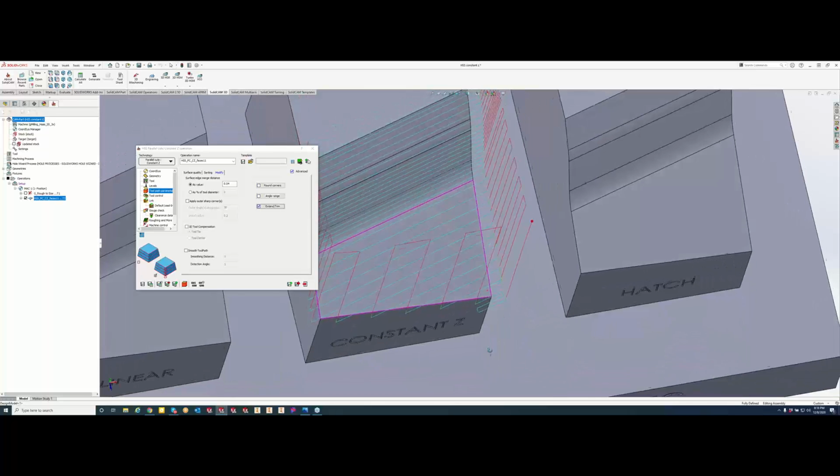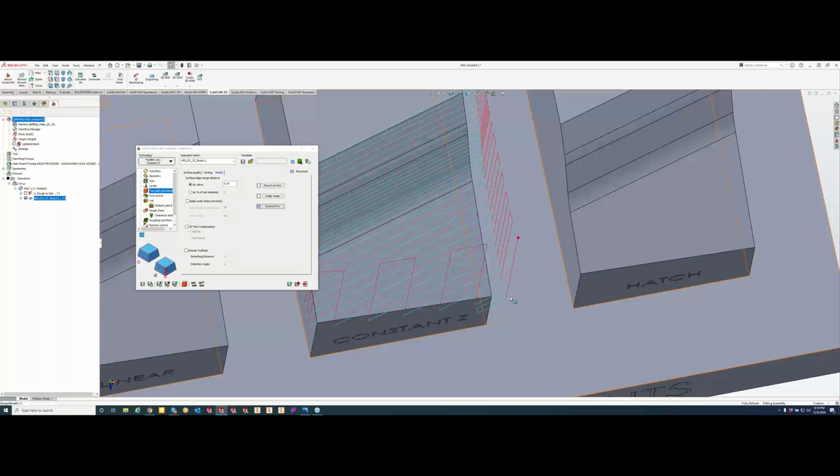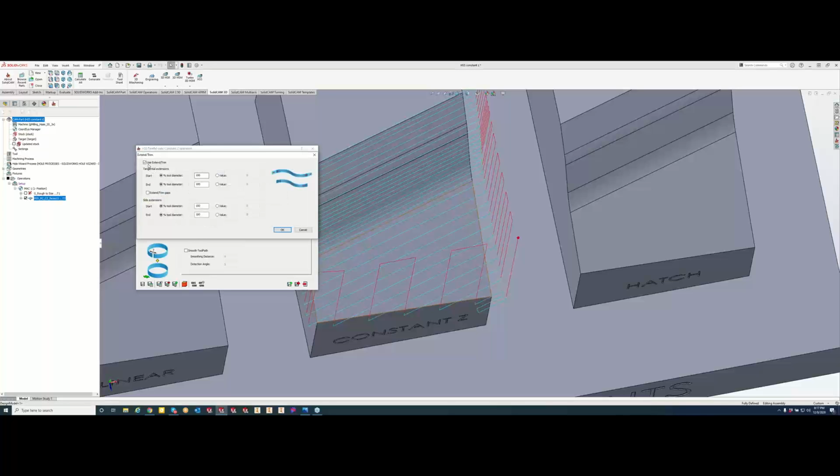And what you're seeing right now is the tool path based off of the center of the ball. So the center of the ball basically is what's happening over here, we're cutting the air. But this does come in handy when you're trying to blend together two surfaces, or just making sure that we get the entirety of that part. So let's just go ahead and turn that off right now.